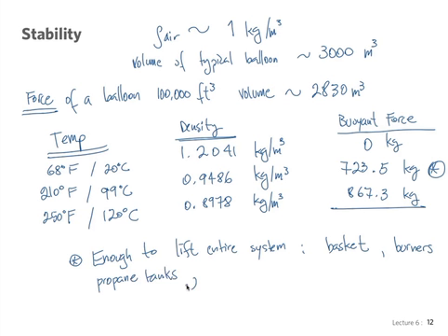The envelope itself, the nylon, is quite heavy. It could be up to 100 kilograms. The envelope of the balloon itself, and up to 5 people. Again, the temperature inside the balloon is not constant. There's a gradient, like I showed you in the previous infrared image, but we can use an average temperature to calculate the forces.